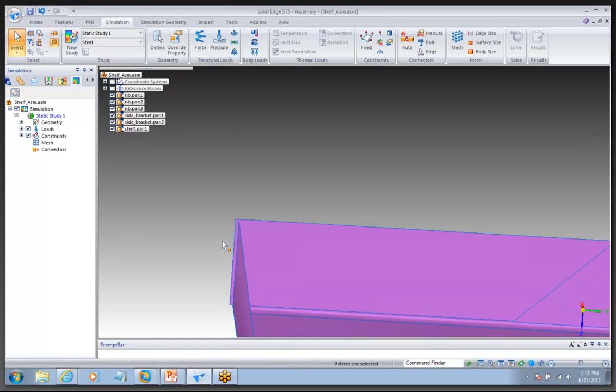So what if I had an edge connection, it's really more accurate. If I had a true edge connection where the 2 edges were line to line, then what I would do is I would extend this surface out and trim it back till they touched, and then I would use our unified body for that. But because this is really a T connection, I can use my edge connection and feel good about my results there.